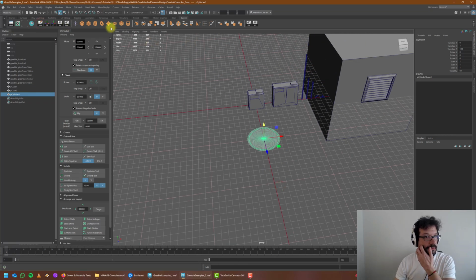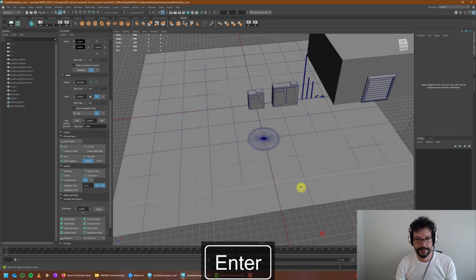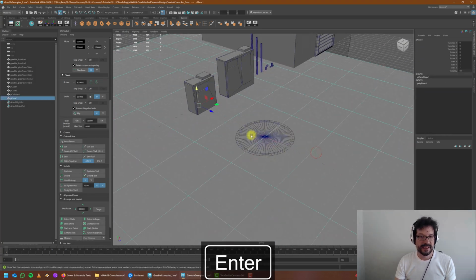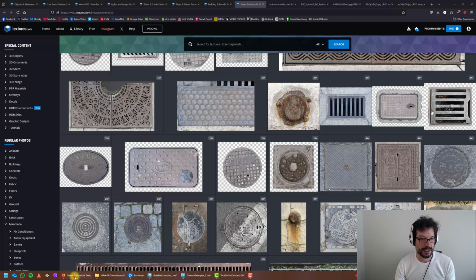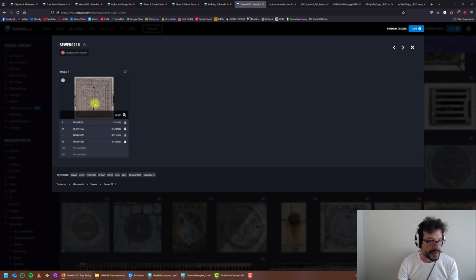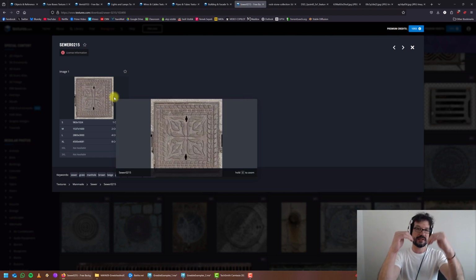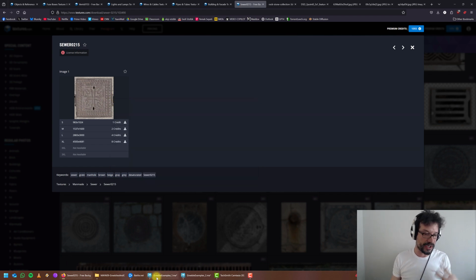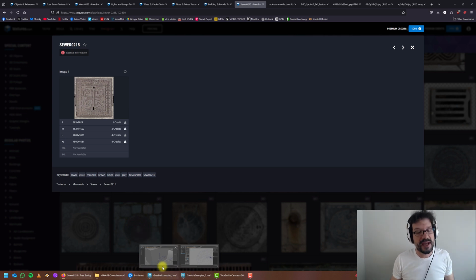So when I create a ground plane, it remains flat with it. But here's the issue: we have lost that indentation, the kind of indentation these manhole covers have around them. Check it out, every single one of them has it, and there's a good reason for that. These manhole covers are supposed to open, so there is a disconnect between the part that opens and the frame of it. That indentation, if you want it as geometry, will be removed. It cannot remain flat.